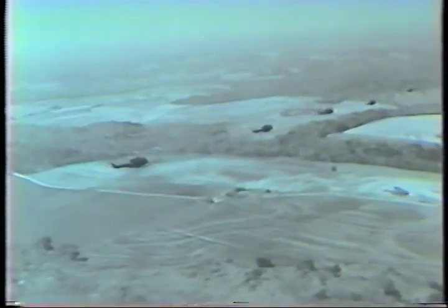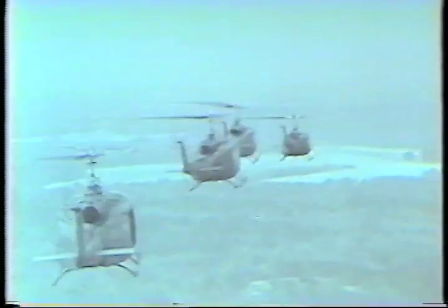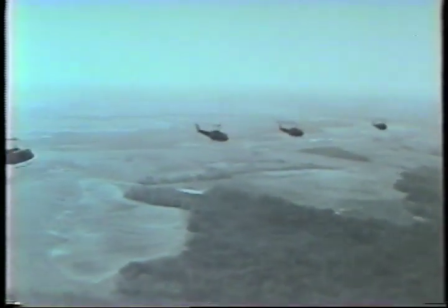When flying in a trail formation, always take caution to retain the required 2 helicopter length separation. A misjudging of this requirement usually results from an aircraft flying too close to the lead aircraft, and deceleration may be necessary. Often in correcting this situation, an excessive amount of aircraft cyclic is applied, causing an abrupt deceleration. This abrupt deceleration multiplies as each trailing aircraft corrects for the change. The end result may place the trail aircraft in an excessively nose-high attitude and quite often causes him to leave the formation.